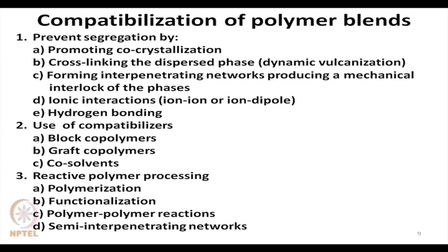Then after filling the mold, the polymer filled mold is cooled at a specified rate of cooling. Now, that specified rate of cooling affects this molecular alignment or organizes these molecules to have this long range order in the product.